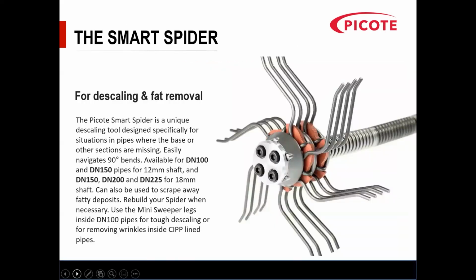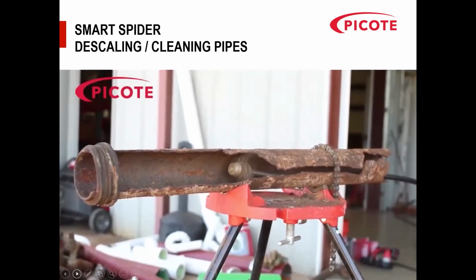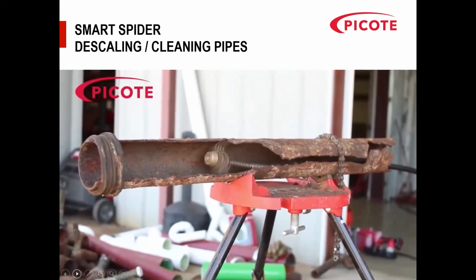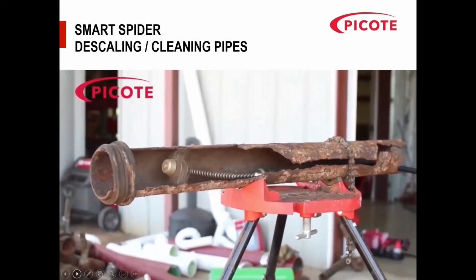Smart Spider is great. We do it in 4 sizes. It's great for descaling pipes that are in very poor condition or where a section of the pipe's missing. Little video here. Now, in normal life, this would be buried. You would struggle to get a jetting machine through here. You'd struggle to get a CCTV camera through there. So you need to be able to camera it so you can select the repair method.